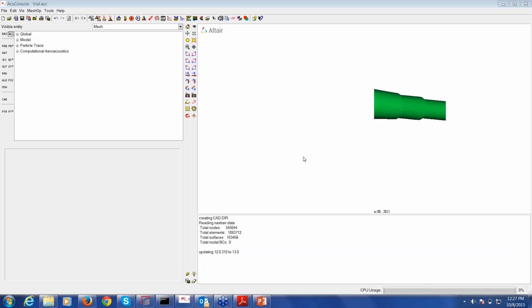There's a question, how to generate a cavity mesh from the CAD model. I didn't understand. So basically from the CAD, the pipe, I have already shown you how to import the geometry and how to do the meshing directly. So it is one and the same. You just need to do the volume mesh. It will generate the surface mesh and then do the volume mesh. Okay.